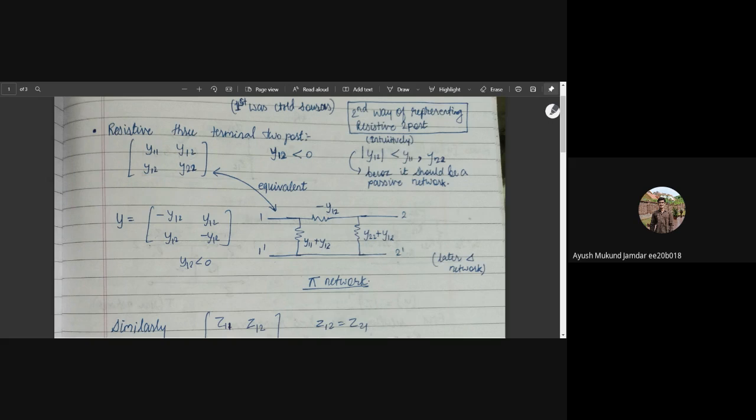For example, let's say we have V1 and V2 expressed as I1 and I2, column vector pairs, I'm talking about the Z parameter matrix. So we can just represent the first port of the two-port with, let's say, a resistor Z1 and a current-controlled voltage source Z12 times I2 connected in series, and that will give us an equivalent first port. Similarly for the second port. This can be applied for the Y, G, H parameters as well, just using parallel and series connections of resistors, conductances, and controlled sources.